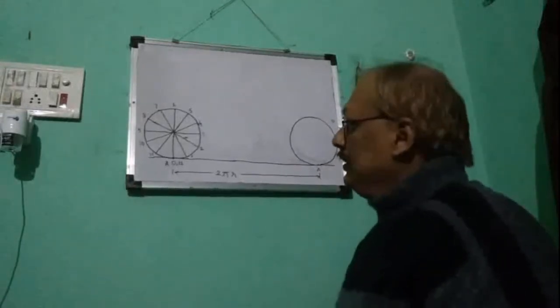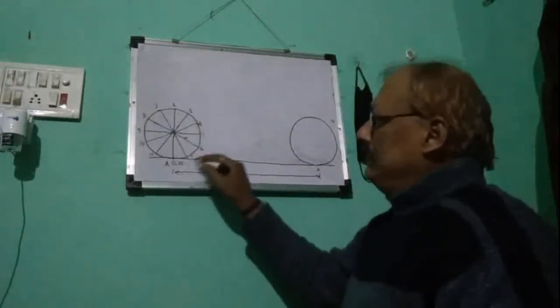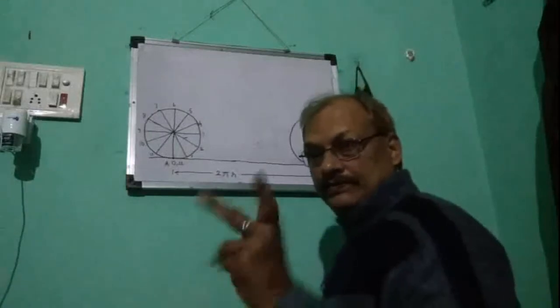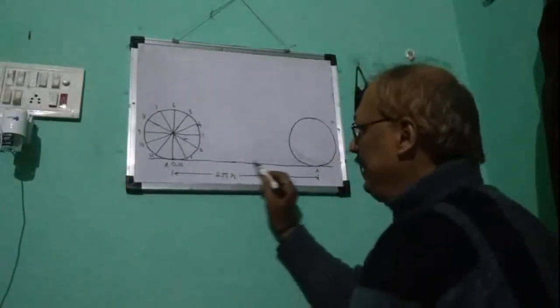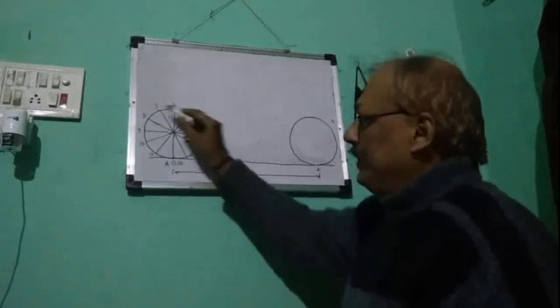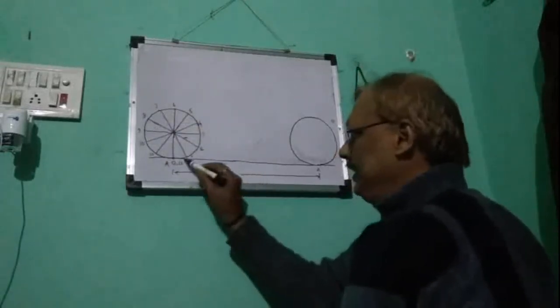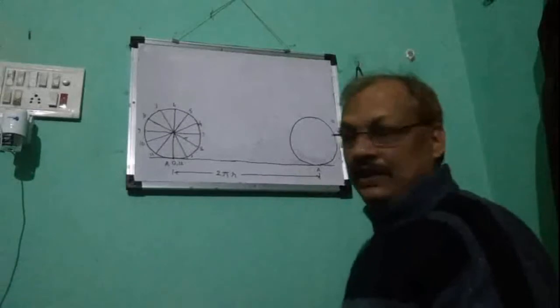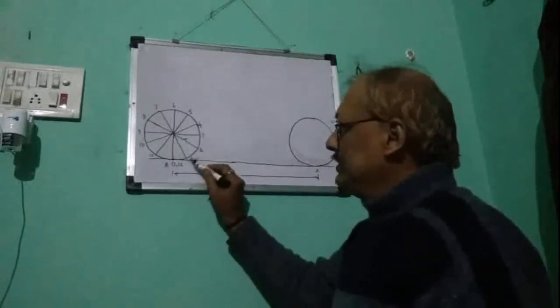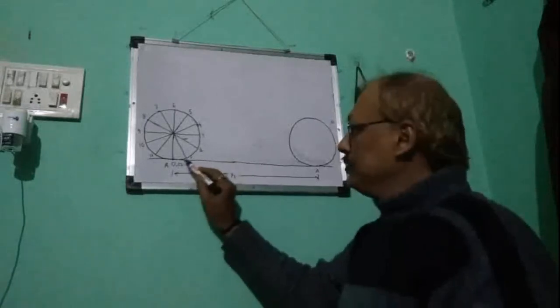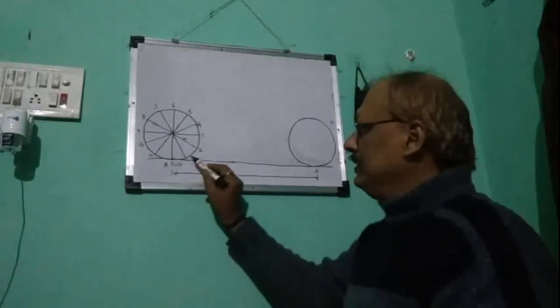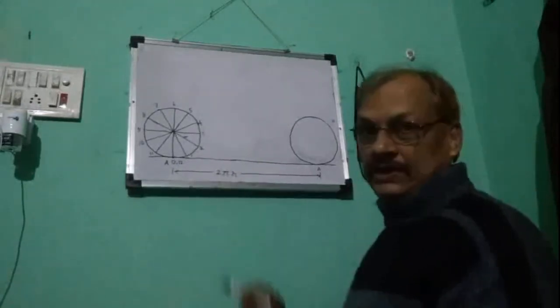Okay, so this circle is divided into 12 equal parts. This 2 pi r is the length of the rolled line. Corresponding points we will make here: 1, so 1 dash on this; 2, so when it rolls, 2 will fall on 2 dash. So those will be equal to 0, 1, 1, 2, 2, 3, isn't it?